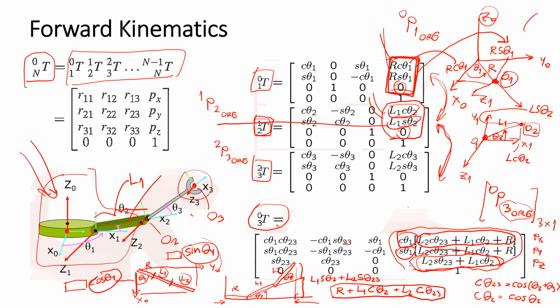But for some industrial robot that has maybe 6 degrees of freedom and is a lot more complicated, if you don't want to solve it by hand, you just compute the matrix of each homogeneous transform and put everything in a computer program. It's a lot more helpful for a bigger number of degrees of freedom. But by understanding the physical meaning, you can cross-check your answer of the matrix by this.